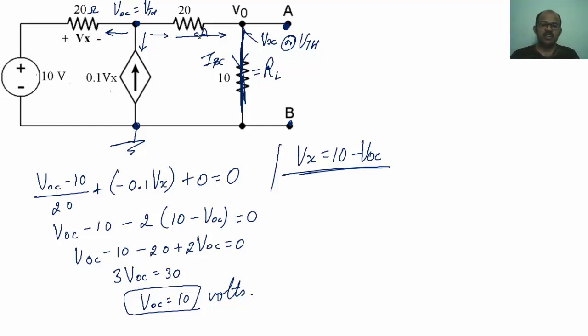Now look at over here. Whatever the current that is flowing over here, the same current will be flowing in this 20 ohms also. So this will be my short circuit current, that is ISC. So I have to calculate the value of short circuit current. In order to calculate it, let me assume this node as Vx, because we are going to consider this 20 ohm also. So this potential will not be equal to VOC, it will differ. So let me apply nodal analysis over here. Let me consider this one as Vxy, because Vx1 is one more terminal, right? So Vxy, let me take.